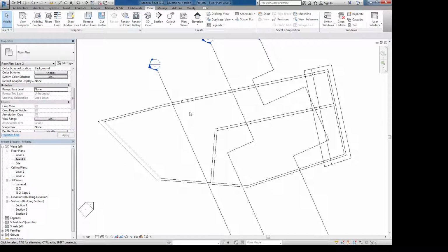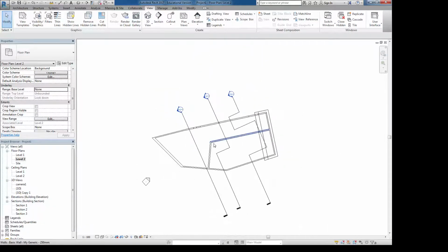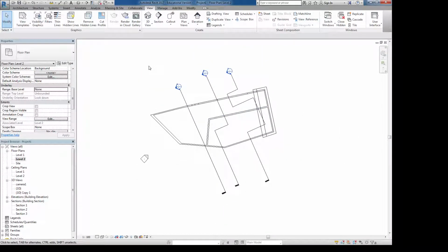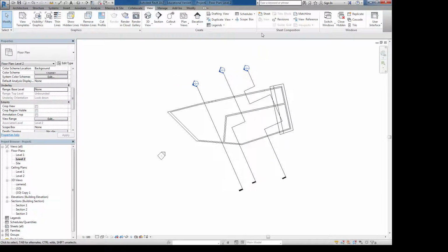I showed you guys the section box, and then the last thing about the views is the sheets. You can export your views directly, but you can also export sheets, and sheets are more defined and standardized. So it's always better to export sheets and keep exporting those and replace the existing PDF, not the views, because you may always move your views around, and that may give you a bit of issue sometimes.